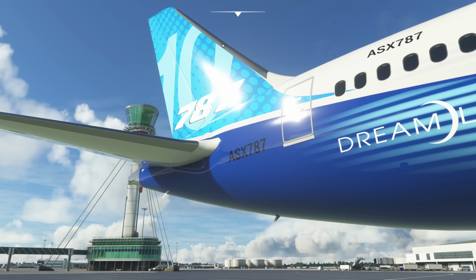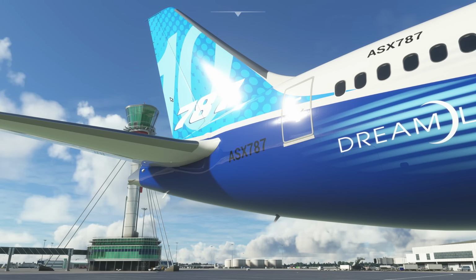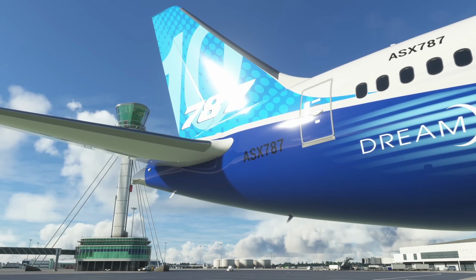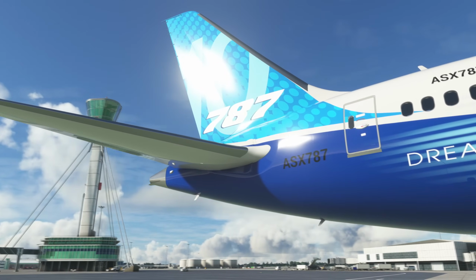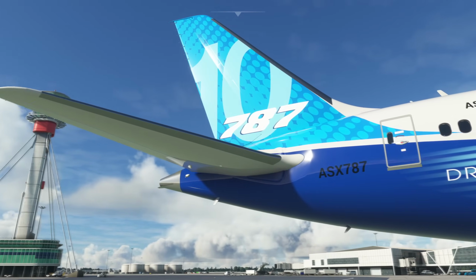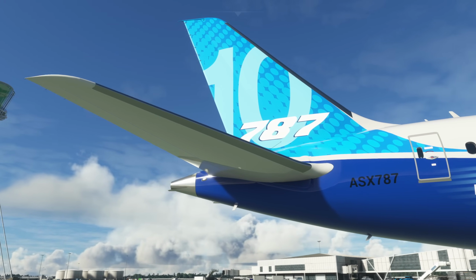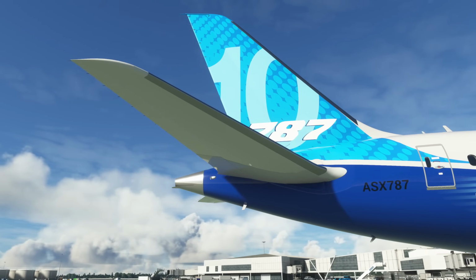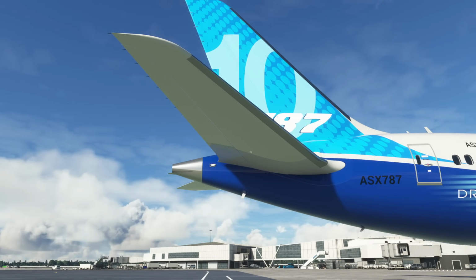But what these static ports allow the aircraft to do is apply counteracting rudder straight away to make sure that doesn't happen. So actually, gusts that cause any sort of rotation of the aircraft are dampened out by the airplane systems. Not entirely, you still have to put some input, but they are damped out. Now, those static ports are a long way up and quite hard to see, actually, but we are checking to make sure they're not damaged or anything obvious going on there.